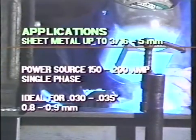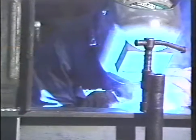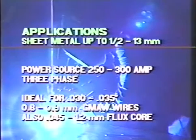Applications. If welding up to 3/16 of an inch, a 150 to 200 amp single-phase power source is sufficient. .035 wire is the most practical choice. A 250 to 300 amp power source is practical on metals up to 1/2 inch. This is typically a 3-phase power source. This is ideal for .035 MIG wires and .045 flux cord wires.